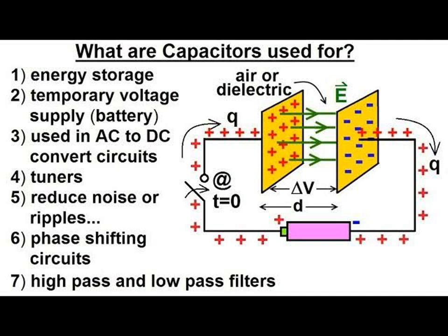So we start with the first one, which is the series arrangement. Assuming I have 3 capacitors arranged in series, C1, C2, C3, with their voltages V1, V2, V3, and then of course a current flowing through them, I1, I2, I3, and then the quantity of energy stored, U1, U2, U3, and then some potential questions are asked. What is the effective capacitance when they're in series? Effective capacitance is simply the reciprocal sum of the capacitors. That's 1 over C effective equals 1 over C1 plus 1 over C2 plus 1 over C3.